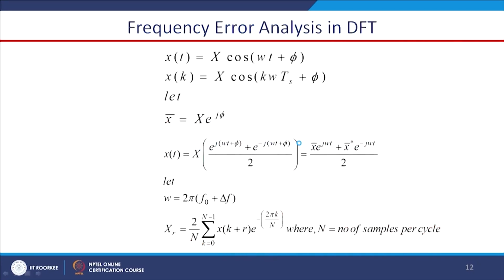Now, this is another part, known as frequency error analysis in DFT. Before going to that, let us just give some remark on this recursive DFT. In case of recursive DFT we observed that we have to calculate the DFT only once, for this first window, and for the rest of the windows we are not going to calculate the DFT from time to time.